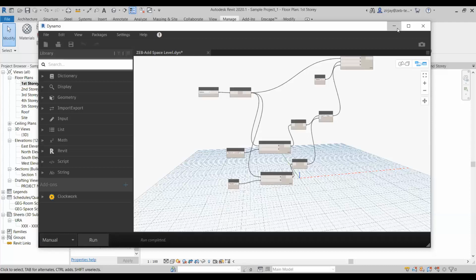Basically, as much as possible, we only use this option, simple. And we want those shading surfaces to translate. All the sunshades that we have created outside the building, we want to translate into IES. So we're choosing this one, simple with shading surfaces. Okay, and then we go to next. Then we just save the file. In this case, I'll just save it here.